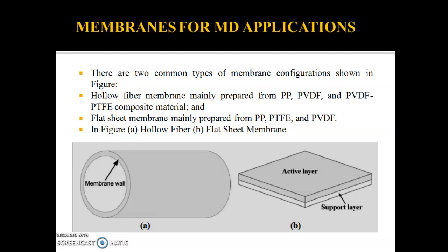However, high flux hollow fiber membranes with different features suitable for membrane distillation have been developed recently, such as dual layer hydrophilic or hydrophobic fibers with a very thin effective hydrophobic PVDF layer, which is having a thickness of 50 micrometer, and hollow fiber membranes with a sponge like structure and thin walls also, which have a flux of around 50 to 70 at 80 to 90 degrees Celsius. This flux is as high as that from flat sheet membrane, right?